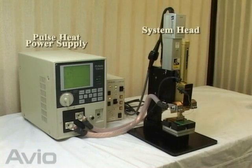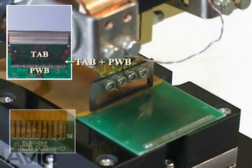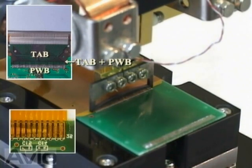This is a process to solder modules onto glass epoxy-based PWB. Pulse heat method is most suitable for soldering flexible substrate, such as the flexible circuit, without lifting at the joining section.